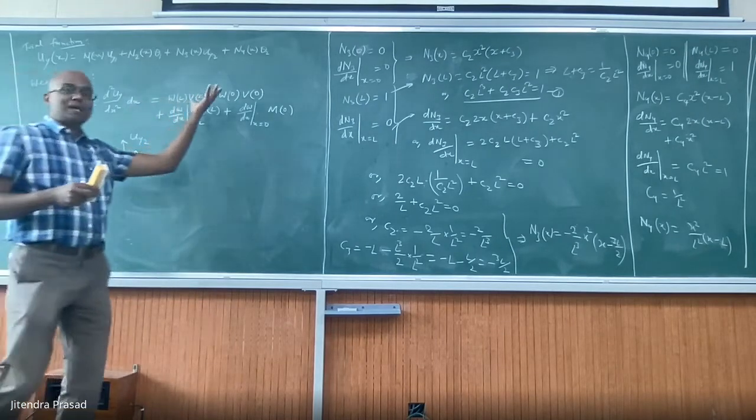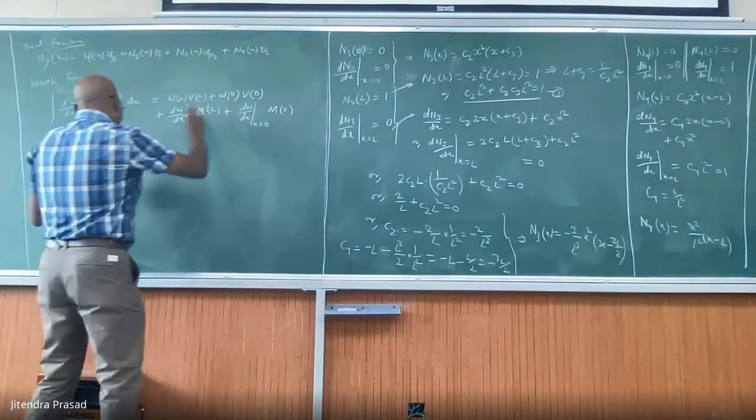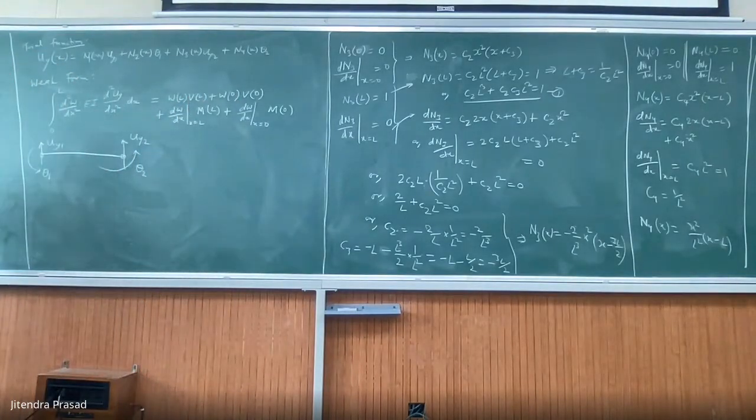Okay, what is the meaning of that? This is the meaning of actual forces that is acting there. So if the force here is acting, say, anti-clockwise, you have to take positive. If the force here is clockwise, then you have to take negative. There are two senses. One is the way we said M: we said this and this is positive, we call it the bending moment is positive.